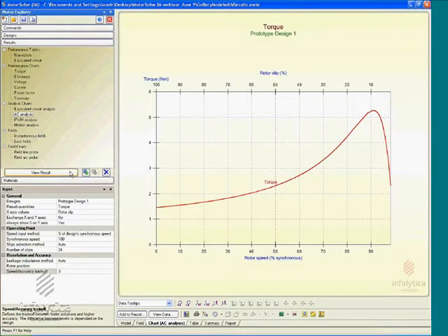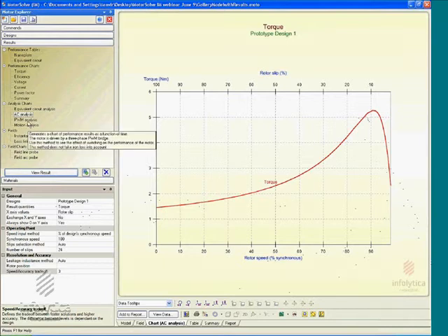And another very interesting and powerful feature of this is that the algorithm for this software will automatically scan through regions of the vicinity of points of rotor speed where the equivalent circuit parameters change steeply, and will automatically take more points into account in computing results in those regions, which could be over here, where things could be changing rapidly, as opposed to in this region where things are linear, or in this region where things are changing rather gradually. And the software automatically takes these variations of the rate at which the equivalent circuit parameters change into account.